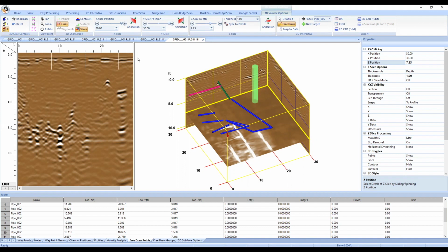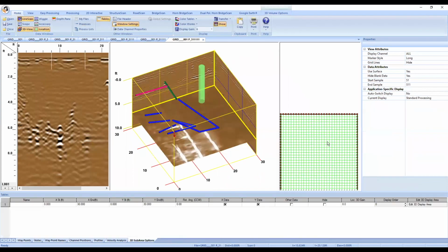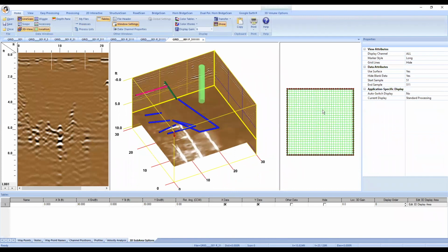You just tell it the dimensions of the grid, add the lines, the profile spacing is determined by the function automatically, and then you have the ability to add GPS coordinates at the end if you have them. If you don't do it at that step, that's okay. We did also see that we could add GPS points at any time in this location data window here. The window looks the same no matter where you do it, but this is where we're going to start our 3D assembly. We're going to start with 3D batch of files.